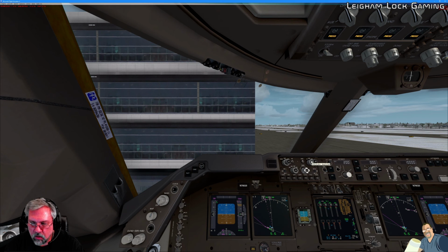So we'll set 3021 barometric pressure. One too far, back up, 3021. That would seem to align with what the altitude indication is as far as ground level. So that would seem to still be correct.